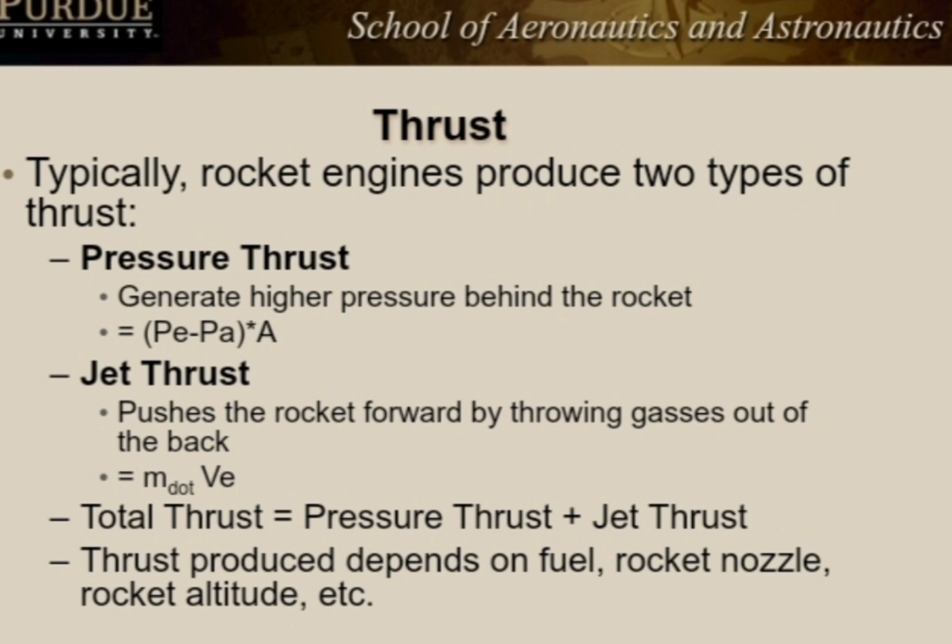To calculate the total thrust, you just add the pressure thrust plus the jet thrust. Keep in mind that generating thrust depends on fuel, rocket nozzle, and rocket altitude.